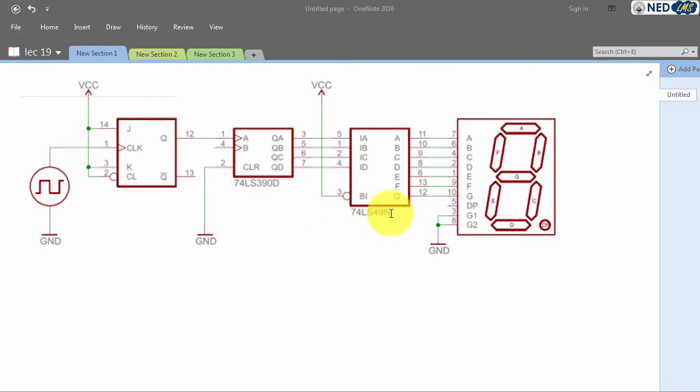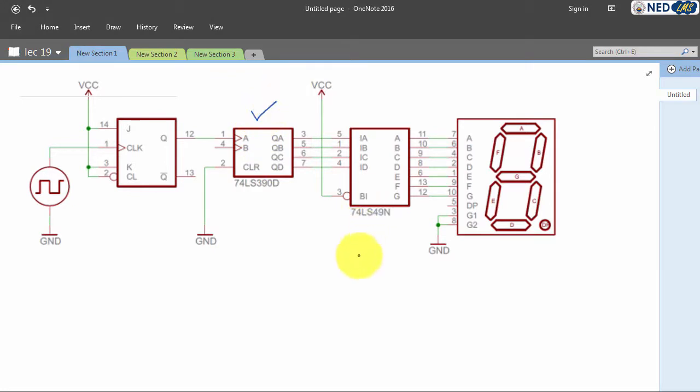Let's suppose as an example that in this IC, I'm not saying it actually provides that, but suppose that this IC can provide 40 milliamps of current to maintain the true or logic 1 or high output. Let's say I have another IC over here, and this IC requires 20 milliamps of current, and this IC also requires 20 milliamps of current over here.